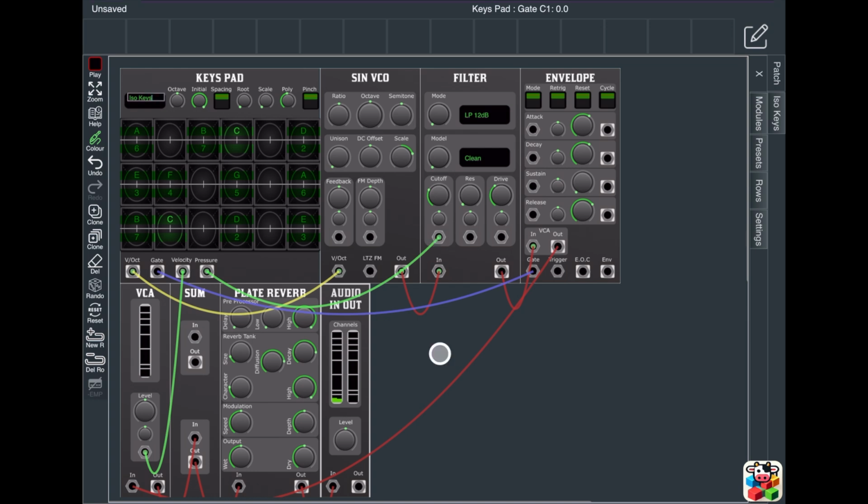Before we can play our patch, we just have to set our modules up. Our VCA module will control the loudness of each note. Here, whenever we see 2 knobs together and a jack, these all act as a single control. The large knob will allow us to adjust the value manually. There'll be a signal sent by this cable, and then the amount of influence this signal has is controlled by the small attenuator. Turning it to the right will give you a positive change, turning this to the left a negative change. For this example, fully clockwise, the velocity has the maximum effect.